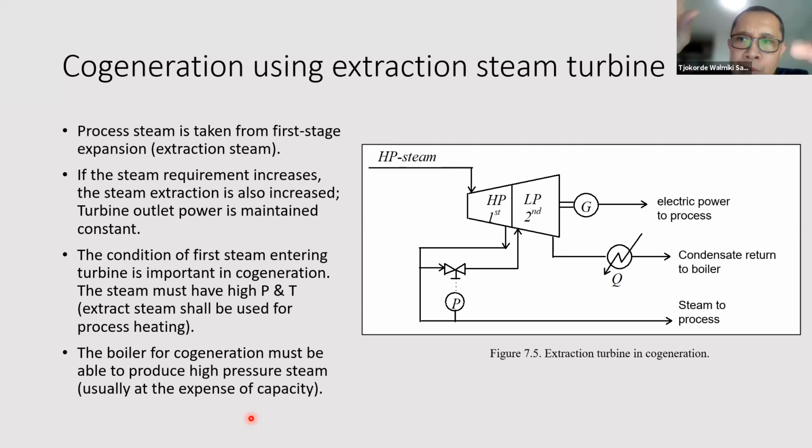How will you decrease the pressure and temperature from one header to the next level down? Are you going to just use a throttling valve, a pressure reducing valve, or are you going to install a turbine like this, for example? There are an infinite number of solutions actually. That's an engineering job.